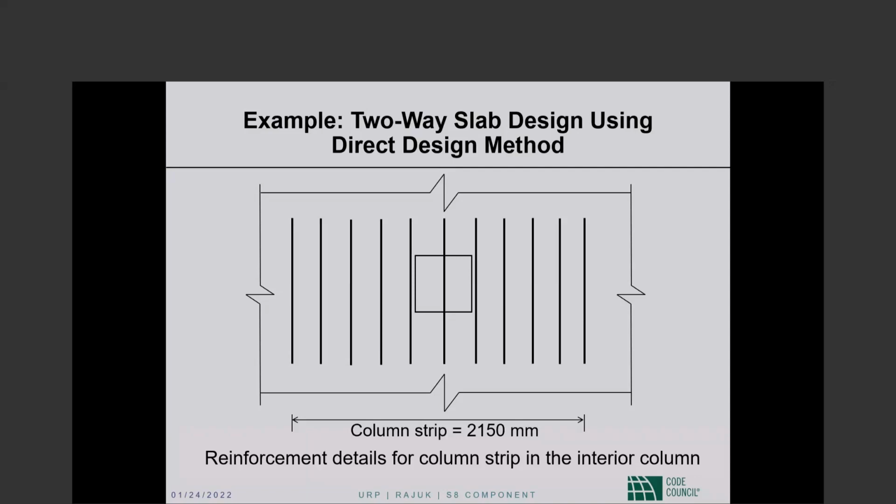But bend bars would require a certain depth. I don't know that there is a code prescribed depth. I think in the case of slabs, there actually is. I forget now, 6 inches and 16 times the bar diameter, something like that. There is a provision for it. You cannot use bend bars even if you want to, unless your slab thickness is beyond a certain minimum. And I cannot remember whether it is 6 inches or 8 inches.